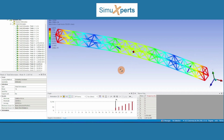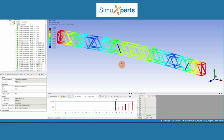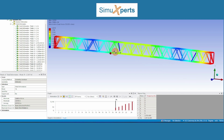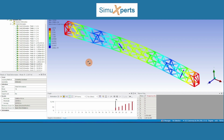This is exactly what I meant by our model should have only one body. It should display only 6 rigid body modes. This model has 2 disconnected bodies, so it's a total of 3 bodies in our model, the main one, and 2 anomalies. And that's why we get 18 rigid body modes before we get to mode 19, which is the first flexible mode. So this concludes the presentation for this first model, which presents 2 anomalies, 2 bodies that are not connected at all to the rest of the structure.